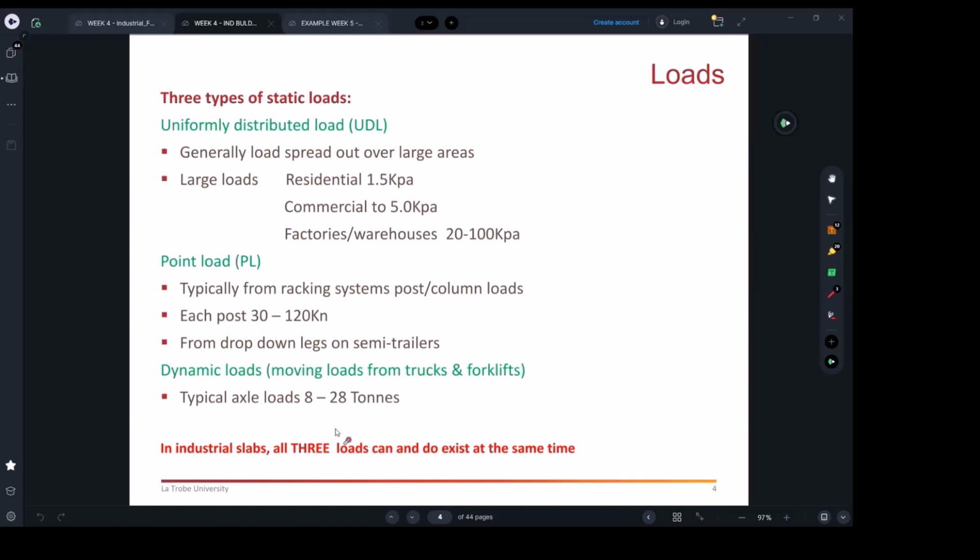Like maybe if we said the static load is 20 kPa, let's talk about point load. If we said a static point load is 30, and you want to worry about dynamic, because a forklift at 1 point load weighs 30 kilonewton, for example. But then you're worried about dynamic load because that forklift may be moving and suddenly stopping.